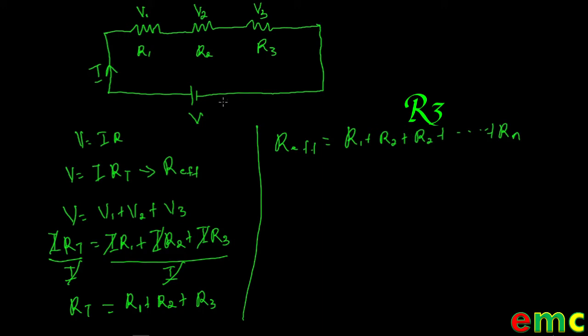The current flowing through a series circuit is the same because there is only one established path for current flow, while the voltage dropped across each of the resistors is different because the resistance of each load is different, and therefore the voltage dropped across each load is proportional to the resistance of each load.